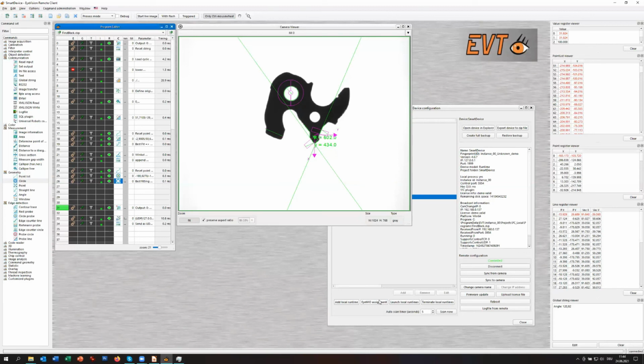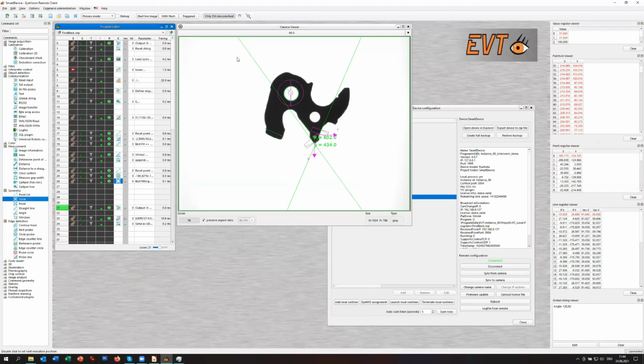Right now we are not calibrated, but I think once again, I know it's repeating always, of course, you have these calibration tools here in the EyeVision software, and if you want to measure calibrated, you simply use the calibration tool to calibrate your field of view. So you can also do the distortion correction if you have not the best lens. Of course, depending on the smart camera, maybe you don't have a very good lens, so distortion correction for the lens might be really good.